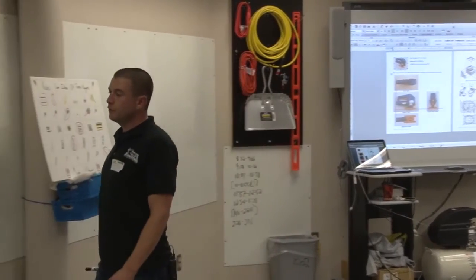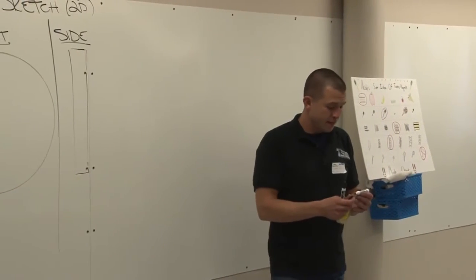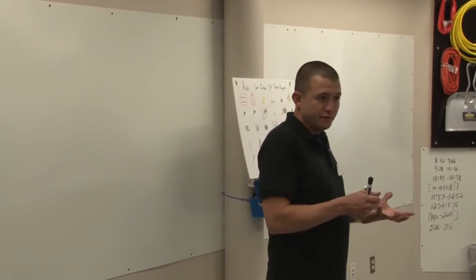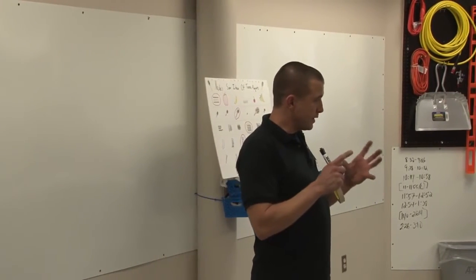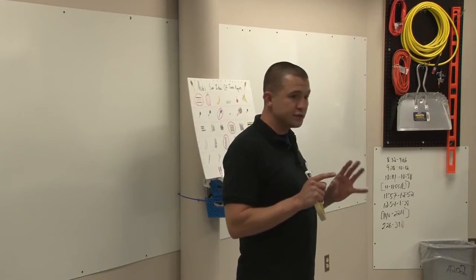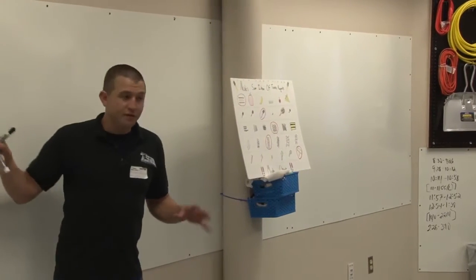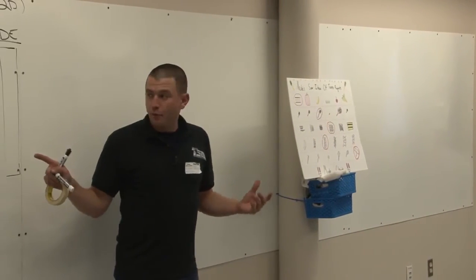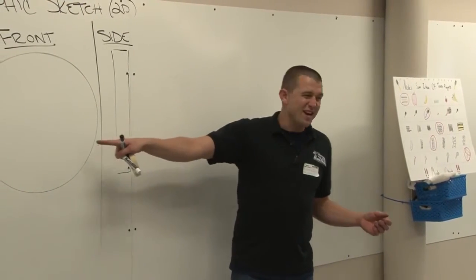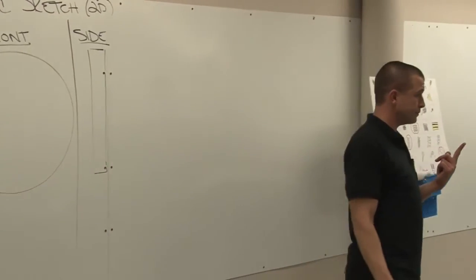And I'm going to now move from drawing the object to putting dimensions on this object. So if I wanted someone at the mint to make my version of this coin, I'd have to give them a picture of the coin as an orthographic where you can see the different views and all the dimensions would have to be there. So they're going to need to know length, width, and height. And if I put a dimension for the height here, because it's right next to the front view, I wouldn't have to put the height here also. We'd only have to do it in one location.